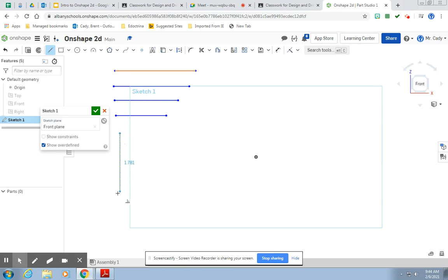Now I'm going to draw 3 vertical lines. See, I did not double click. I right click, escape line, right line. Oh, that line is crooked. So I'm going to undo that line and start it again. There's different ways that we could go back and make that line vertical. For right now, these are some of the basics. So there are my horizontal lines.